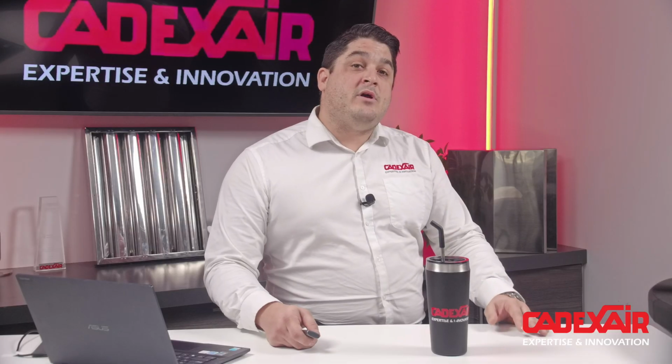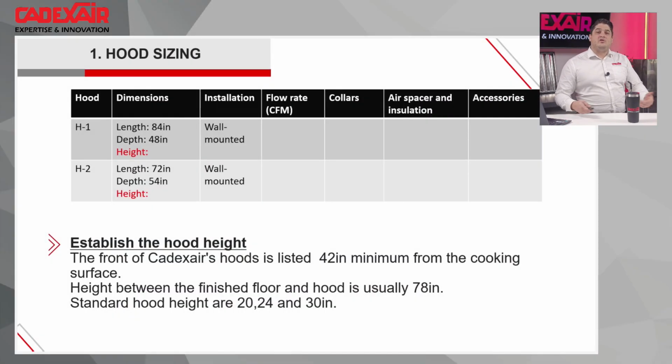So technically, if we are looking at the full design of a kitchen exhaust hood, as per our UL listing, we need to be 42-inch higher than the cooking surface. Almost all cooking surfaces are at 36-inch from the ground, to be easy to operate. So the fryer, the griddle, and everything are almost all like that. So usually the front bottom lip of the hood will be at 78-inch. Everything can be custom made, but I will say the standard in the construction of a hood will be 20, 24, and 30-inch.